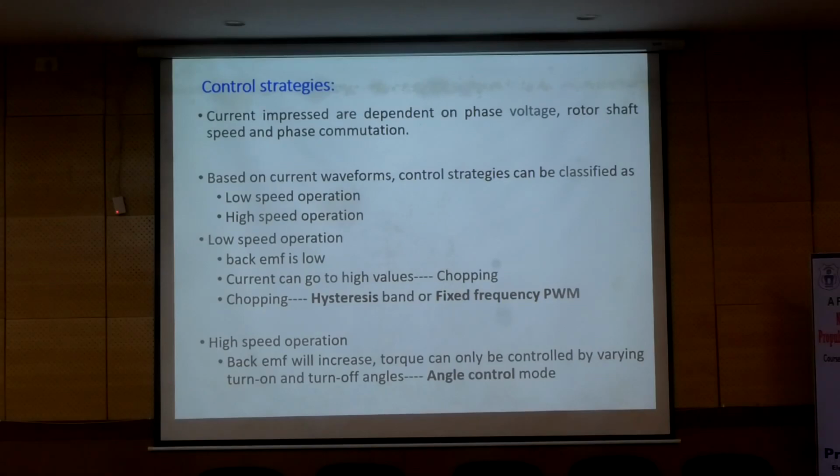This is the basic control strategy phenomena, but there could be various other advanced control mechanisms we can devise, depending on the application also. For example, we have designed a control scheme for this direct PV fed SRM drive, where we used a variable DC based PWM scheme.